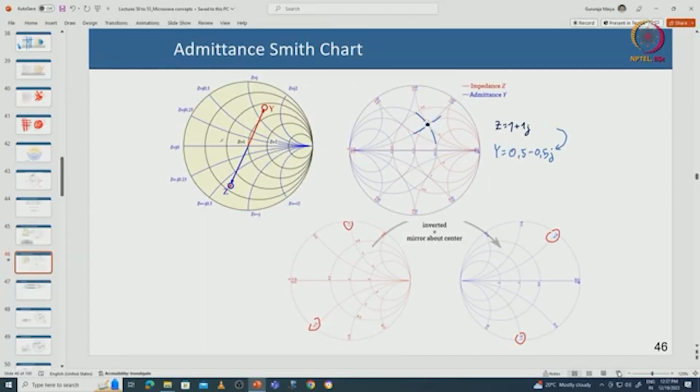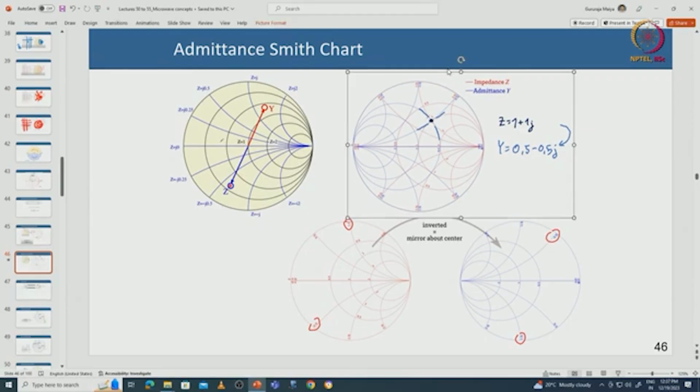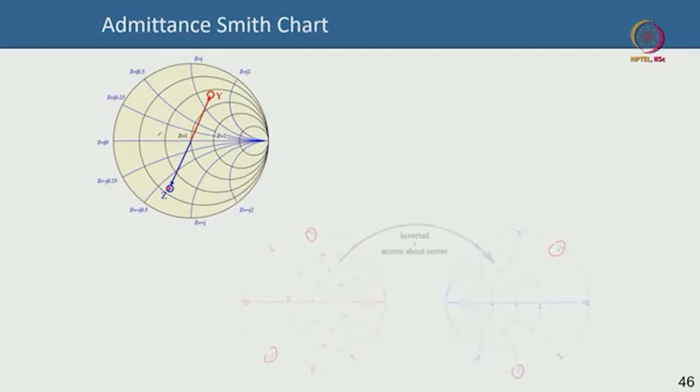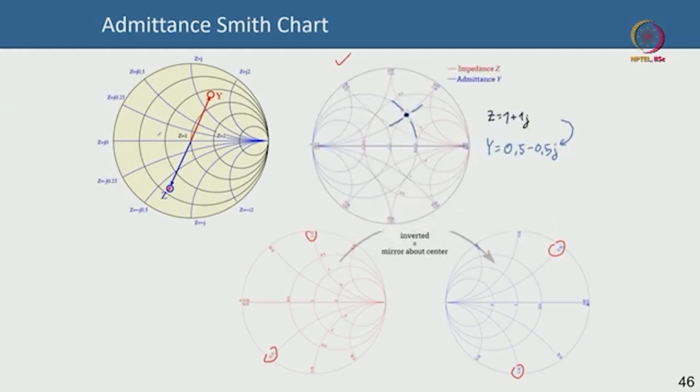Okay. So I am plotting the y and the z Smith chart together in this plot. Sorry, okay, I have to go full screen. I am plotting the y and the z Smith chart together here, this chart. So suppose I have a value here. Now let us focus on the red colored curves, because those are the traditional impedance Smith chart. I go here, this point and then this point. This point corresponds to 1 plus j1 ohm, I mean normalized, sorry, in the impedance.